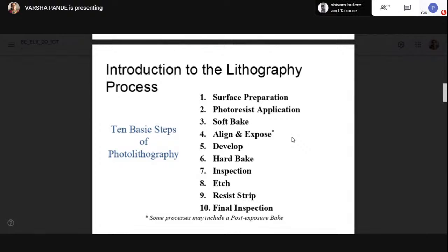Here in this step, either we can etch or we can add something. If we want to add by using the doping process, we can use the diffusion process or the ion implantation process, and through that window we can add the impurity atoms within the substrate. That is nothing but the adding. Or sometimes we want to create the window, then we have to use etching. Once the window is created, through that window we can add or we can etch.